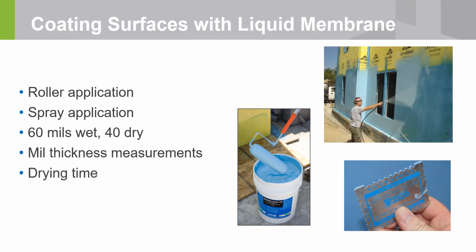And I know that there are manufacturers that push thinner mil products to save money, where they're putting on only 6 mils of membrane, or there are boards and tape systems. So those still don't omit all that labor that's required with guys all over the building sealing up all those joints and irregularities. So the membrane is really kind of extra to add durability and continuity. You're coating the whole building with this thick layer of rubber-like material to really close up all those edges of caulking and tape and whatever.